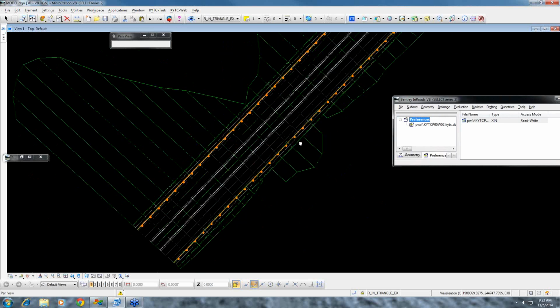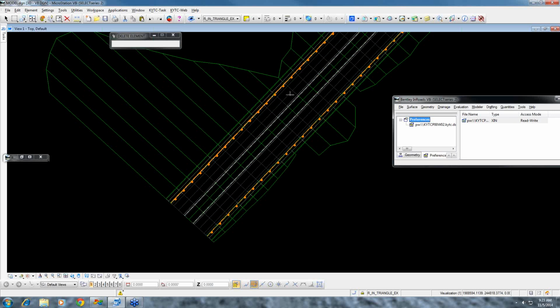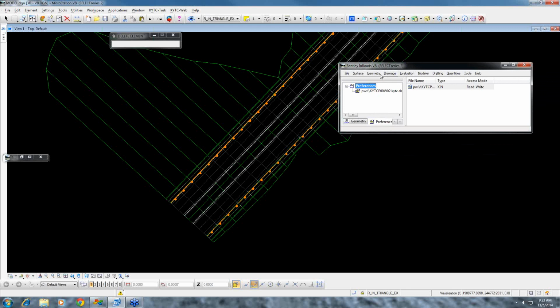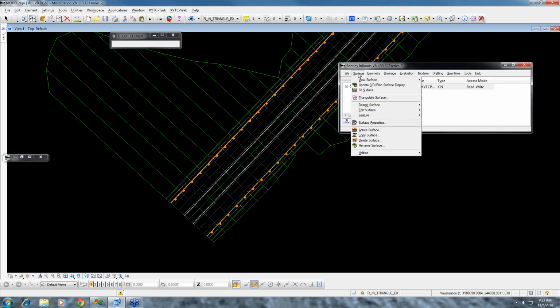Now when we're using these cell tools that I'm going to show you here in just a second, it matters which way these features are placed. The way we run these templates, these are faced in the same direction. So if I place a cell, it's going to be facing towards the road on this one with the guardrail. But over here, it's going to face towards the sidewalk, and that's not what we want. So all we have to do is change the direction of this feature.